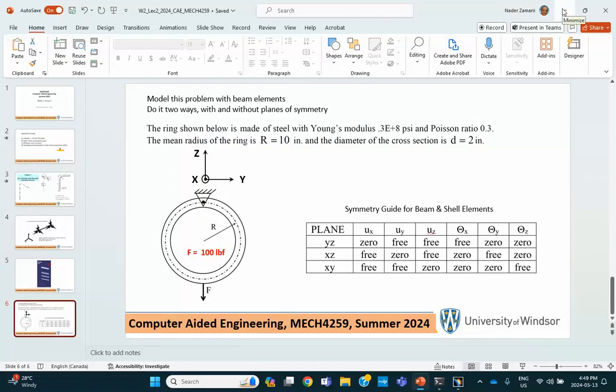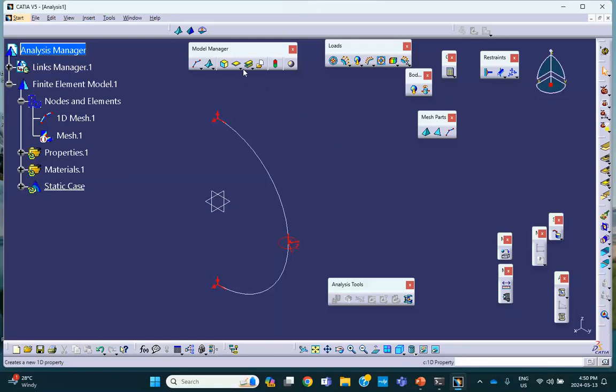Now, I'm going to tell you something that may or may not be obvious to you. Look at this pin configuration. It tells you that it cannot rotate about the z-axis either, right? Because if this is symmetrically pulled down and this is a pin, it cannot rotate about the z-axis. So this last one, I'm going to do another user define.